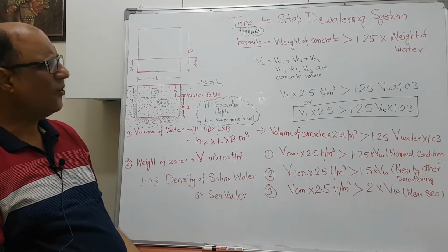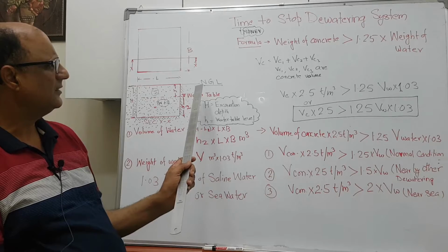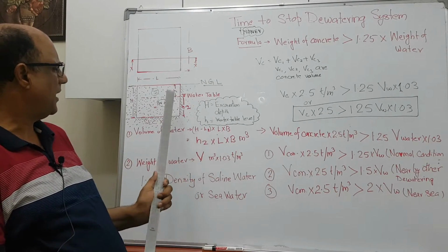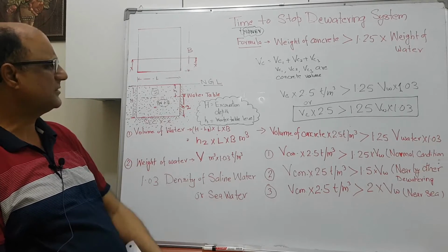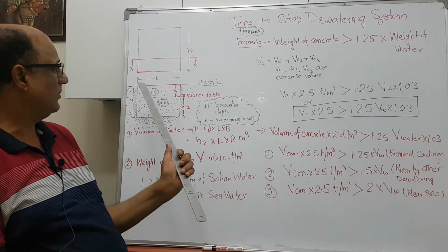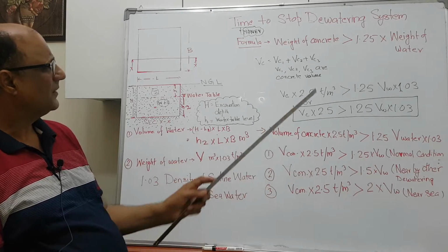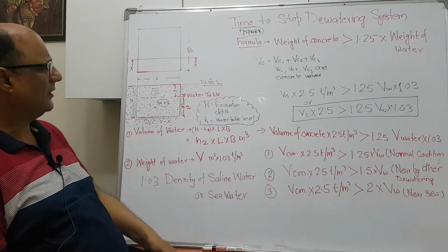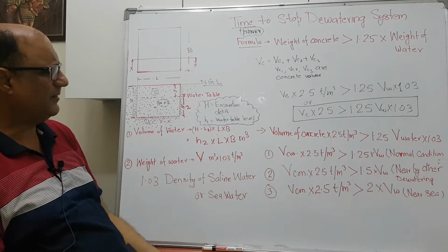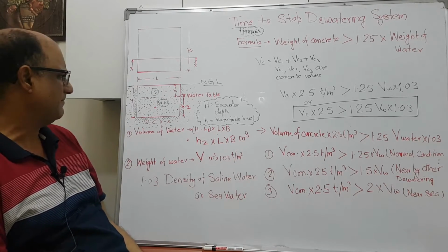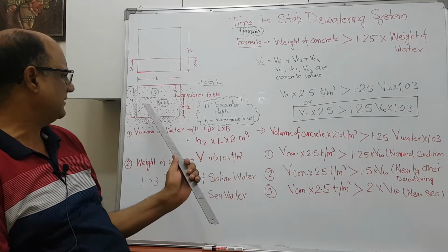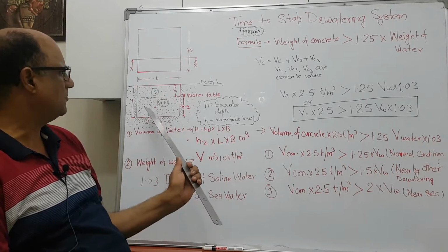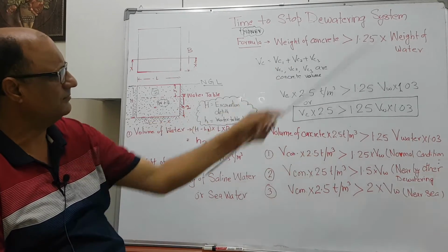is near the sea or the water table is very high, so we cannot do the construction in the water. So we have to remove the water before starting the construction and during the excavation. So the dewatering is required to construct the building underwater, maybe near the sea or in an area where the water table is very high. So we cannot construct anything in the water, we have to remove the water. So the system to remove the water is known as the dewatering system.